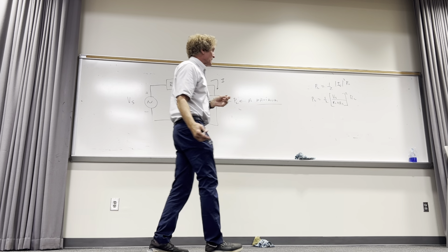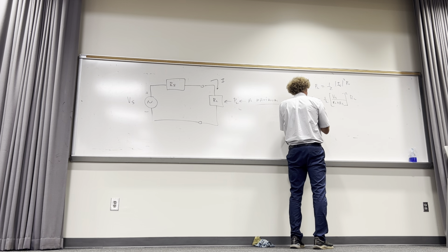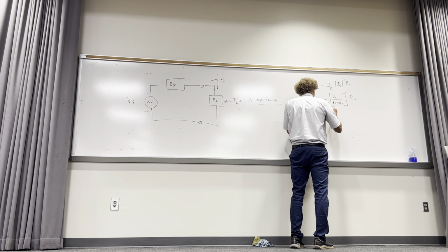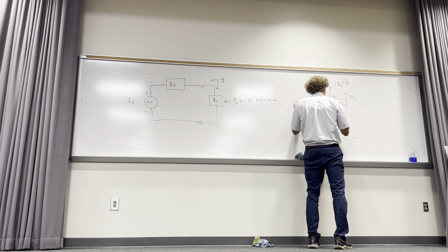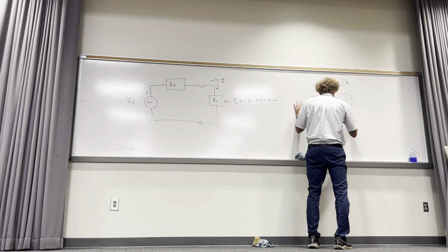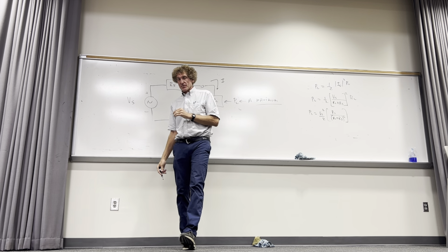I'll take out the things that are constant that can't change. So the power at the load would be equal to Vs squared divided by 2. And then we have RL over RL plus RS squared. Did y'all give me that? After you just do the math.